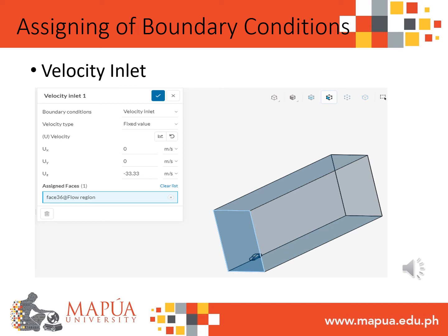The reason for this is that at this speed, it will be easier for us to assess the aerodynamic performance of different car configurations, because at a speed lower than 120 kilometers per hour, the aerodynamic performance of different car configurations will not differ that much. So that's the reason why we set it to 120 kilometers per hour.